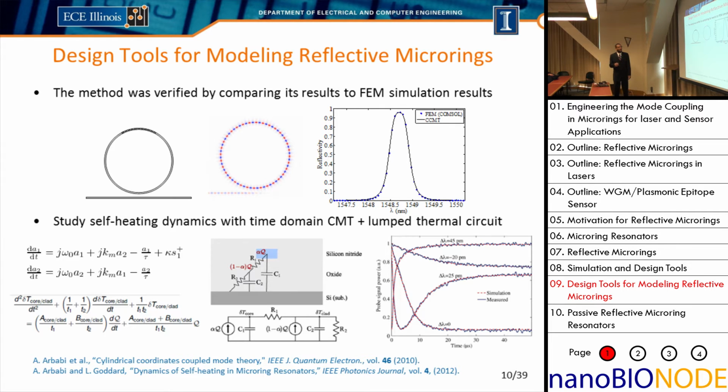And you can see that we have these nice standing waves generated from sending light in and then having it highly reflected. And we get very good agreement between the finite element method in COMSOL and our cylindrical coupled mode theory. Next, we wanted to look at some nonlinear effects.